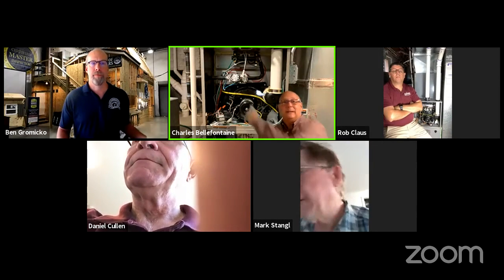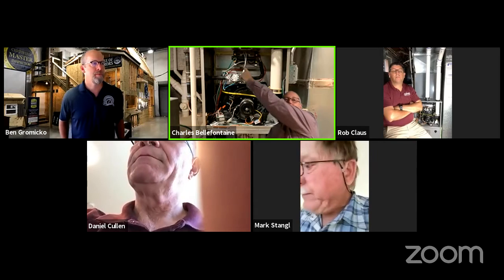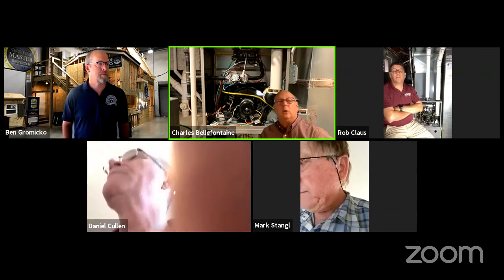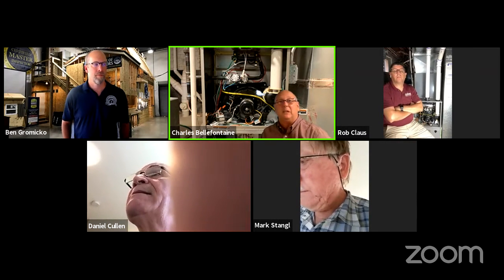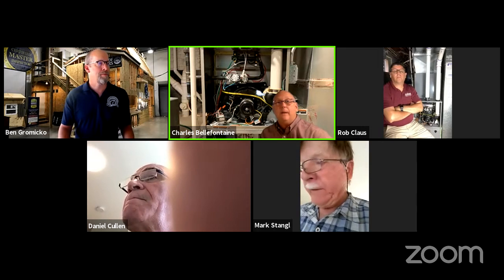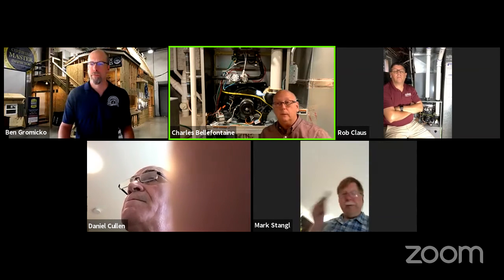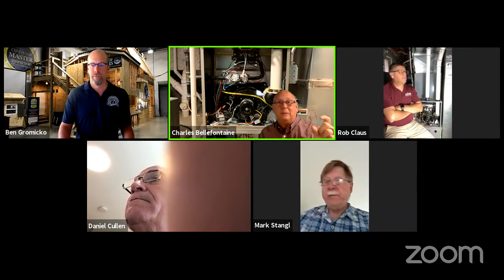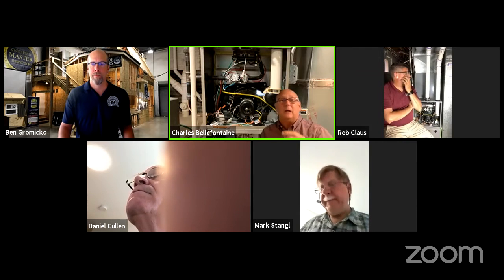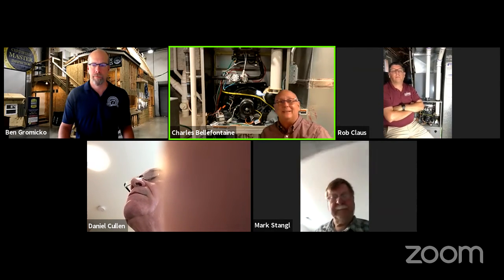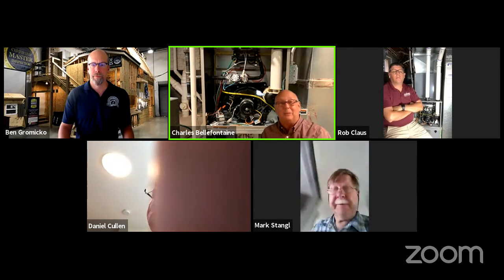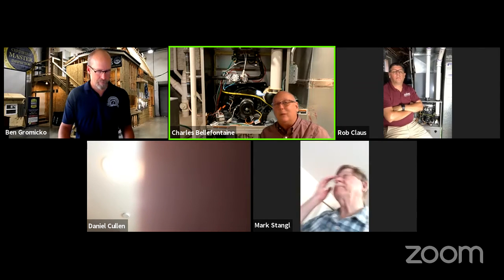Once it gets past that stage, then up at the top is where my burners are. And we're going to have a silicon igniter up there. The next stage is it's going to start glowing orange. Usually the computer lets that happen for about 5-10 seconds. Then it turns on the gas valve and starts sending gas up in there. There's also going to be a flame sensor in there or some sort of thermocouple up in there, something to verify that that gas is ignited. That also sends a signal back to the computer saying, okay, we're good up to this stage and keep moving forward. If we didn't make a fire, then obviously the whole furnace would shut down.